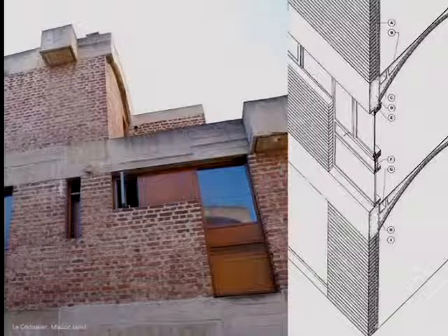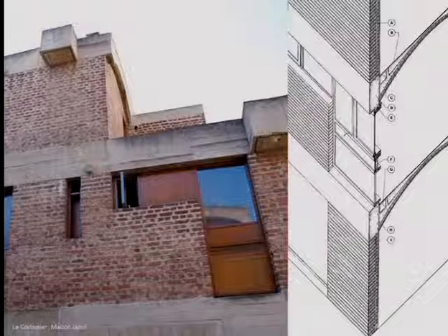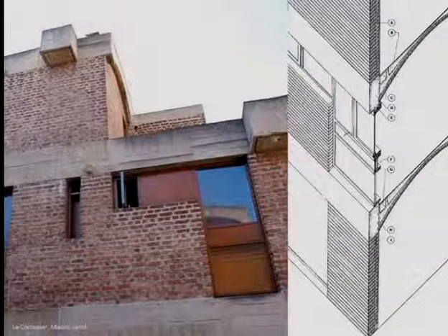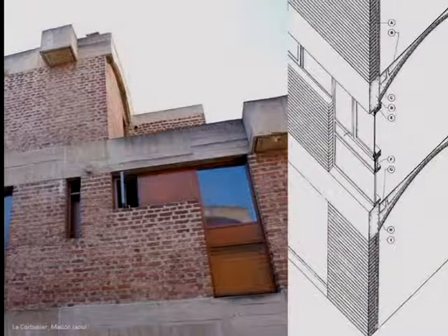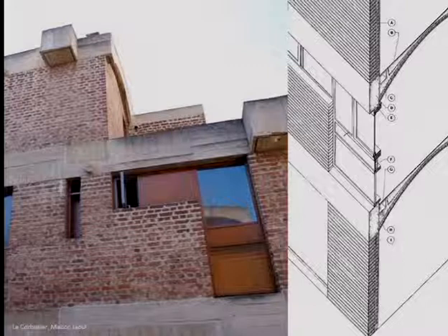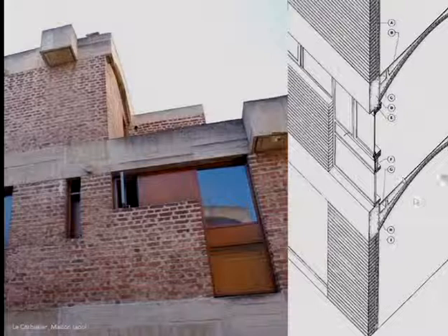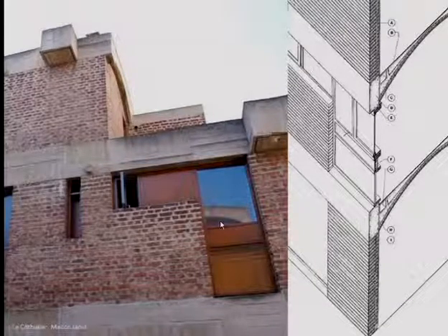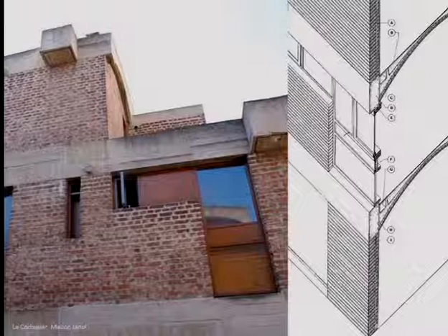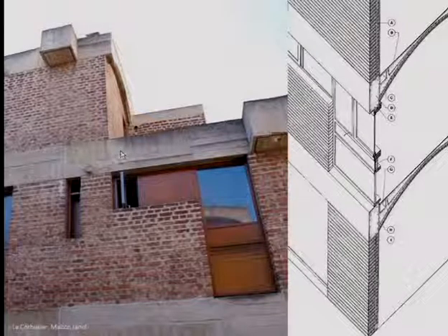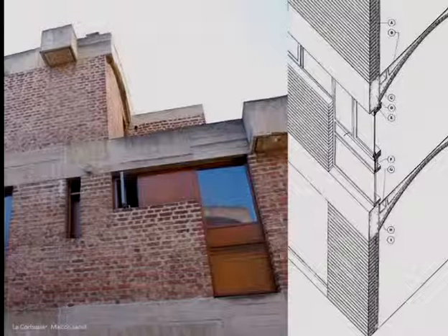But if you do that, you won't see the masonry, the concrete anymore. So you need to find another protection. But so if you want to place insulation on the interior side, you will have a thermal bridge here, which means a loss of heat directly through the structure without possibility of insulating that. All right? So these are all thermal bridges that were probably fine 100 years ago, 60 years ago, 50, not now.